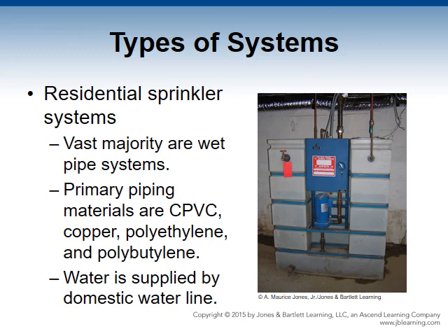Residential sprinkler systems. In order to protect property and life safety, these systems are designed to do the following: prevent flashovers in the room where the fire starts, and improve the occupant's chance for rescue or escape. Manufacturers have gained approval to make dry pipe valves, but the vast majority are still wet pipe systems in residential homes. The main observable difference compared to commercial sprinklers are the pipe fittings, hangers, fasteners, and valves, and residential systems tend to be smaller in diameter and size.